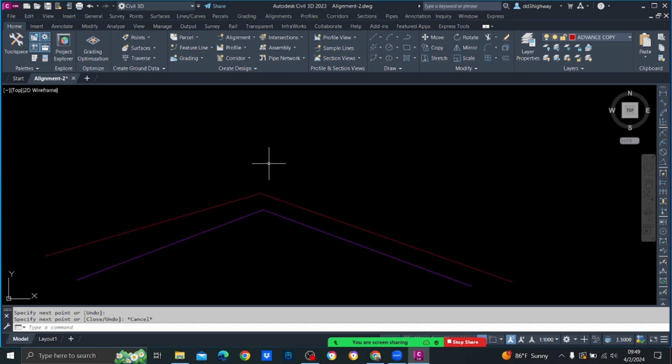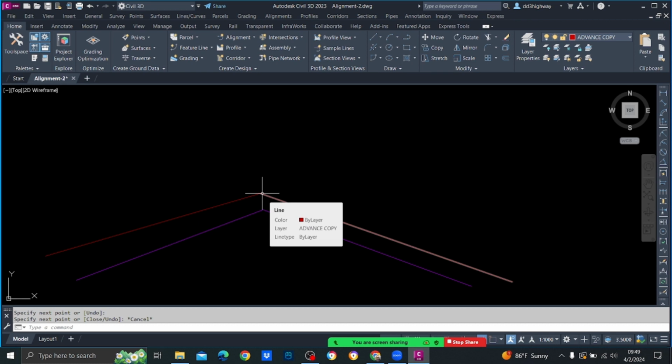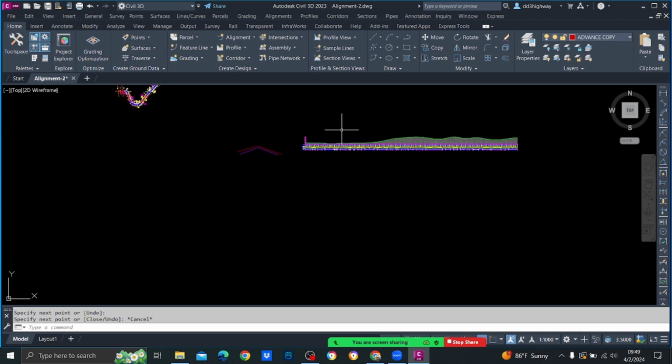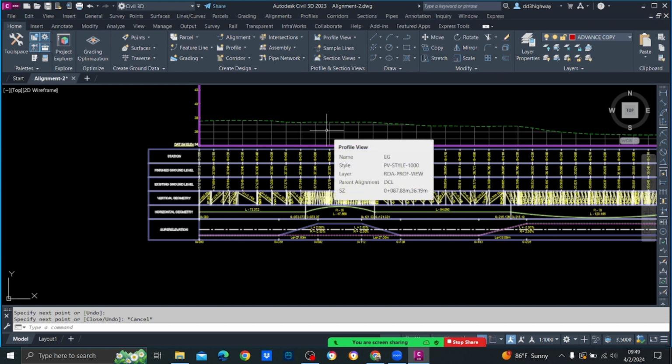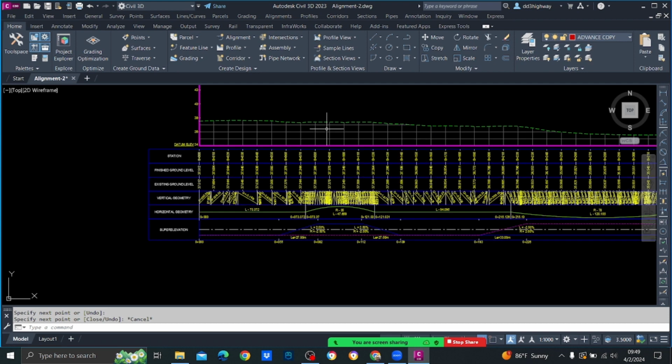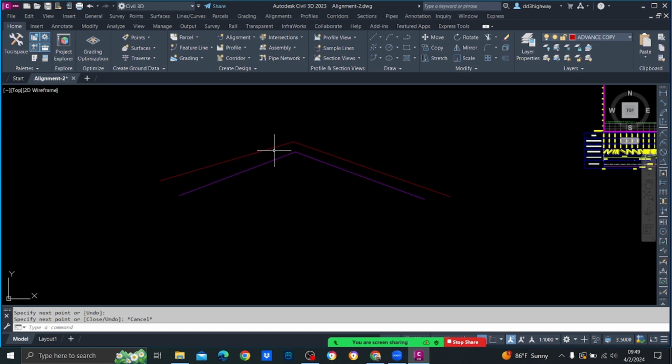Now if you are going to give 100 millimeter thickness on top of the existing road, what happens is in the center line there will be a thickness of 100, so that will be shown here somewhere. Why? We are showing only the levels in the center line. Understand, we are showing the levels in the center line only. Therefore, if your design center line is coming like this, it will show there is a 100 millimeter thickness there. Understood? Then this is not a problem.